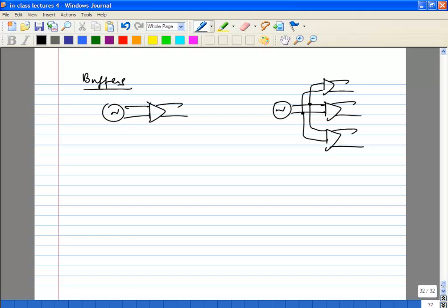Okay, obviously, take the simple case of a PLL. The VCO will need to drive the signal path, which is your mixers, as well as the feedback divider. You definitely don't want interaction between the feedback divider and your mixer, so you will most probably have to separate out these dividers. So you'll definitely have at least 2, maybe more.